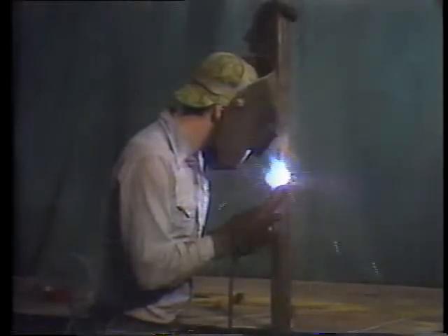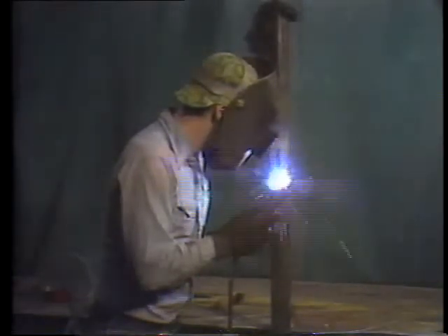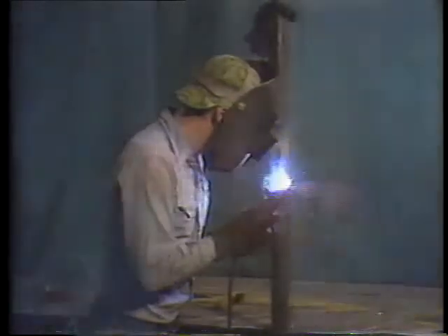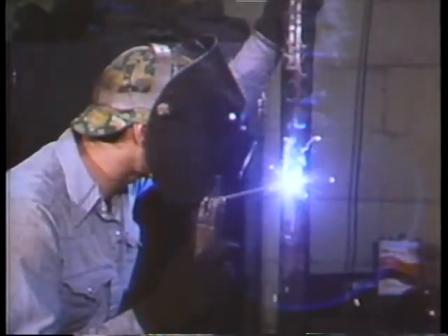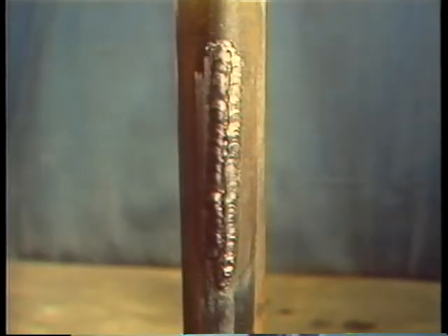Each pass with the weld rod leaves a strip of metal called a bead. The bead is applied lengthwise along the tube. Whenever the bead is stopped, slag is removed by chipping and wire brushing the surface. The procedure is continued until the entire area is covered. The beads should be even so that they have the same thickness throughout. There should be no spaces between the beads, and the thin part of the tube should be covered completely.